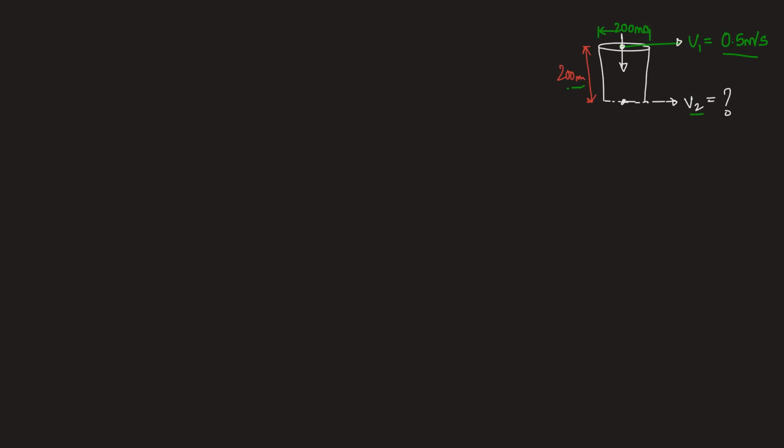at the bottom. Now looking at this figure, you can guess that you will have to apply Bernoulli's equation because we are being given velocity at one point and we have to find the velocity at another point. And there is an elevation difference between the 2 points. Pressure at both these points can be easily identified. It is open to atmosphere, so pressure at both the points will be atmospheric pressure itself.